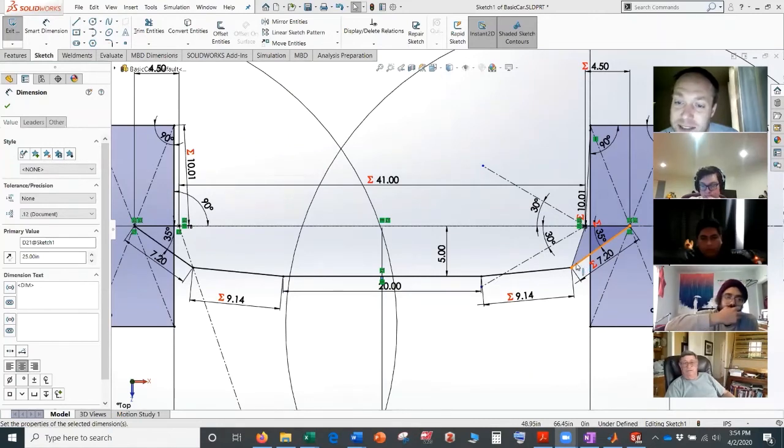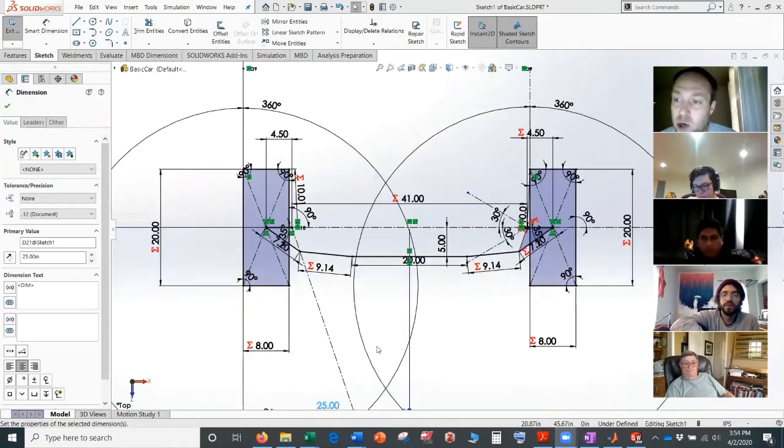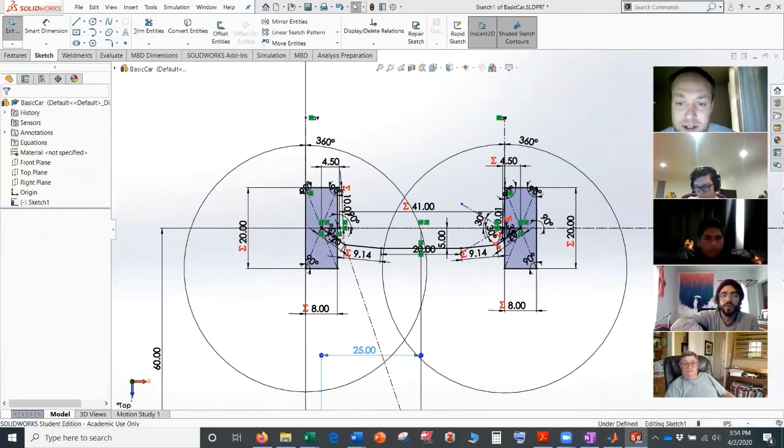So I was looking at this arm versus this arm going over center, but this arm right here doesn't exist. It's actually turning about this point. So it's actually this arm that will go over center with this arm, which basically means when these two arms get in a straight line, you can't go anymore. And you'll see the model breaks at that point for that reason.